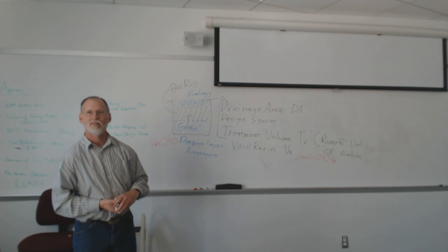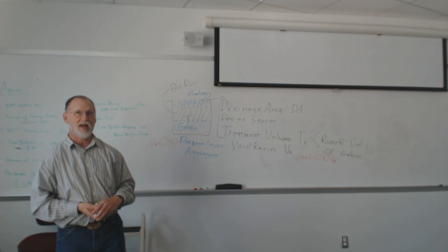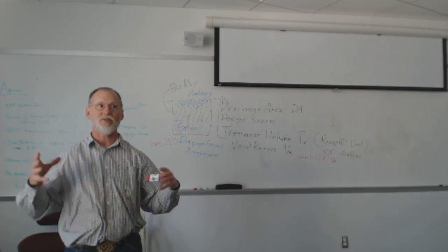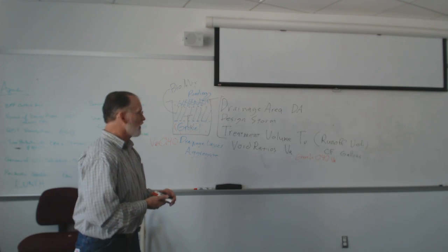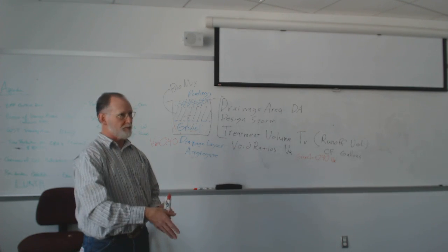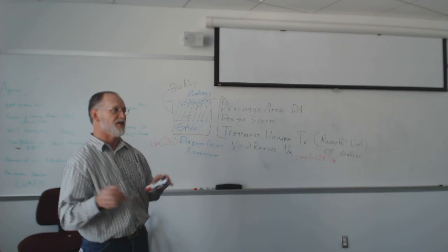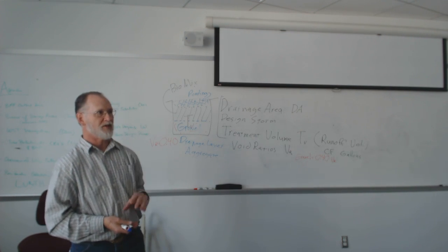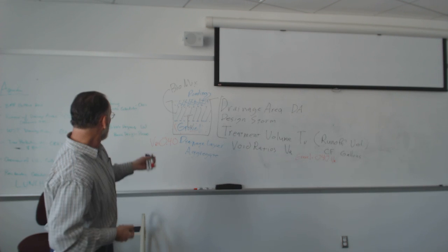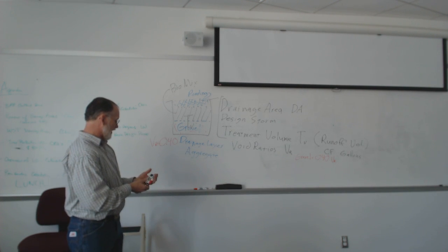So it has more to do with the shape and the gradation of the stone. So that's why it has to be that open graded stone that I talked about. So number 57, number 7s, number 2s, there's a lot of different ones out there. Number 57s and number 7s are the 2 that I'll be talking about in this course. Okay? So that's our aggregate void ratio.